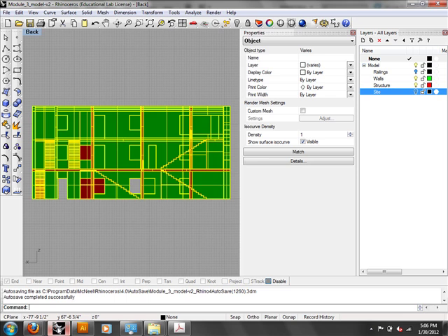Yeah. This is again why we're kind of misusing the tool. The only thing I can think of is you're just going to have to deal with those lines. You might sort out those lines that you know are real lines but show up as hidden. You might just put them on that layer. You might go in Illustrator and actually have to sort them out. It's hard because if you've got something that's visible but extends in front of you and behind you, you can't turn it off because you want to see it. Ideally you turn off whatever you can't see, whatever's behind you.